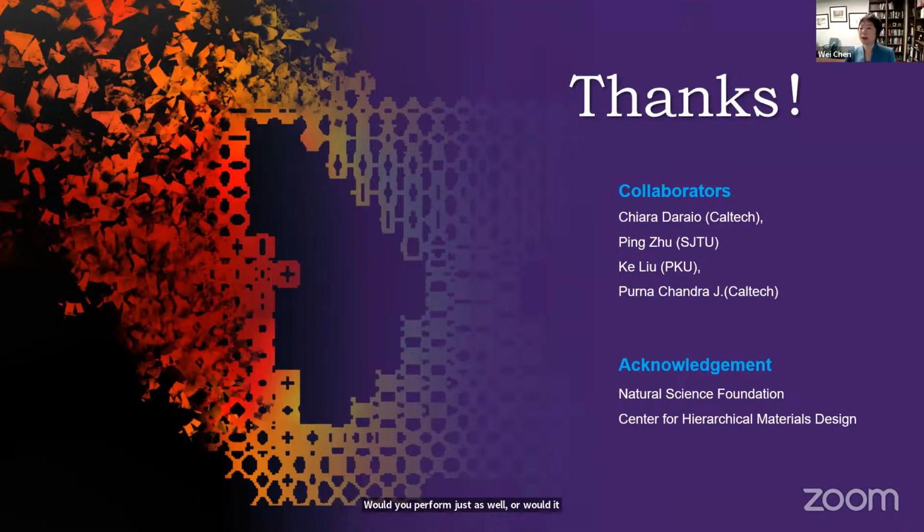I don't think it is restricted to isotropic behavior. It can be used for other kinds of unit cell design, if that's your question. I think the key here is to have a set of targets that you're able to optimize at the top level, and that you also make sure they're compatible at the end. Would it degrade performance if you used isotropic? Yes, I think so, you're right. We just used the database we had, which was orthotropic, but we can extend it to other databases.